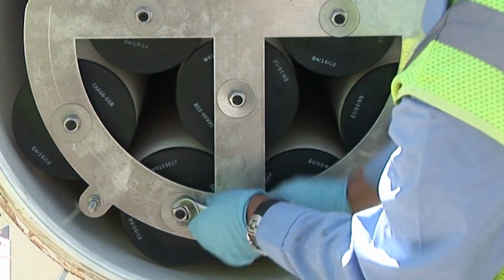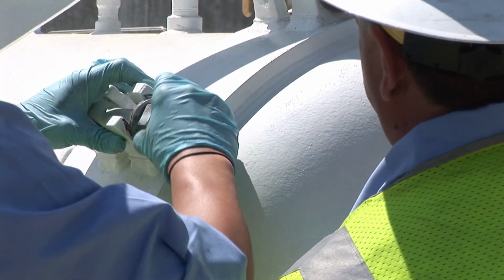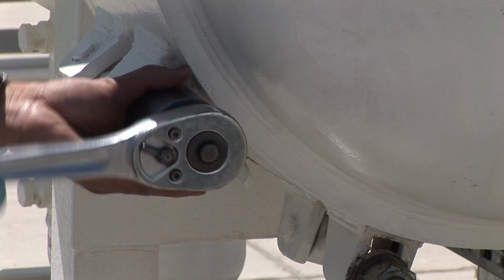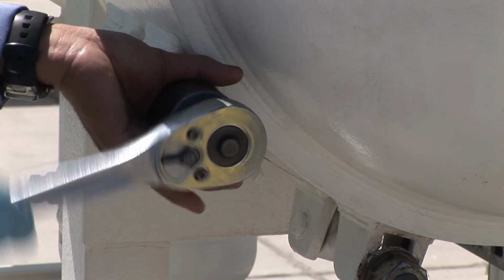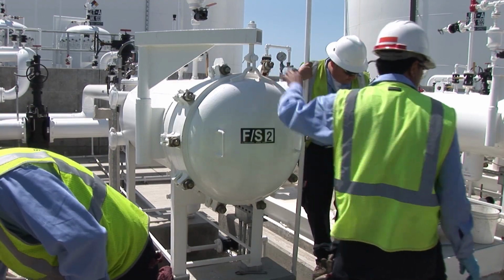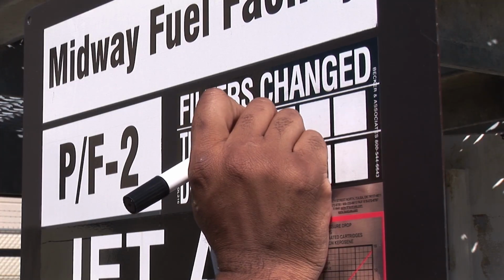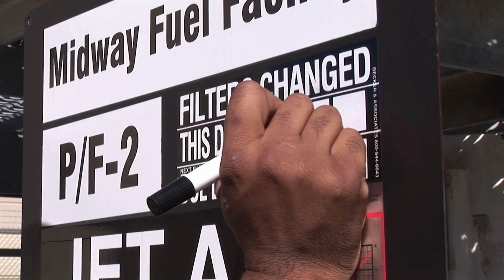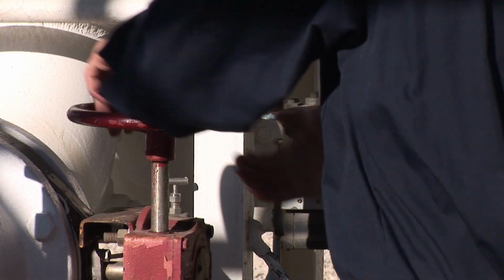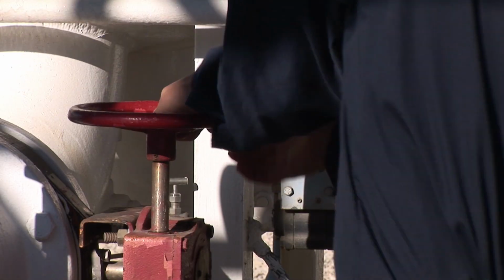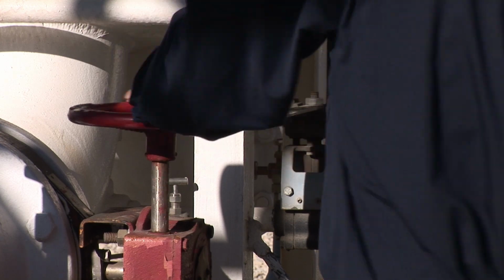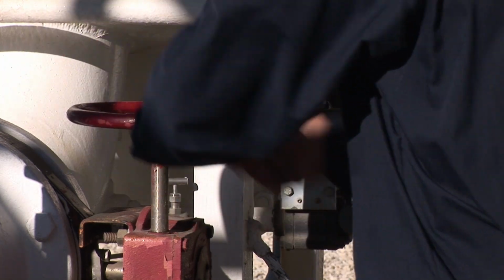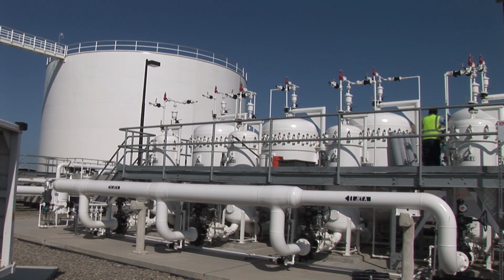With the cover gaskets in place, carefully close the cover. Secure the closure to the proper torque value using a star pattern to tighten. Replace any accessories that you might have removed. Update the cartridge change date and complete all filter records. Now you're ready to slowly refill the housing. Leave the automatic air eliminator or vent valve open during filling. Without any leaks, you should be clean and back online.